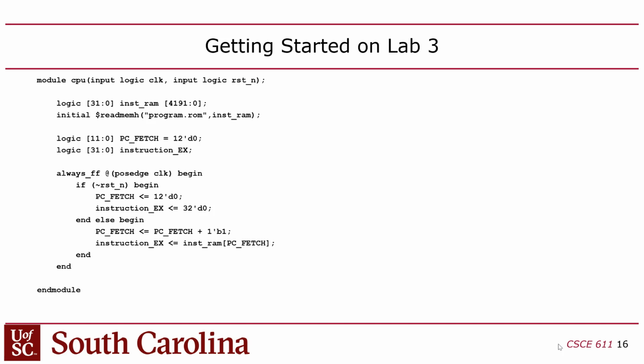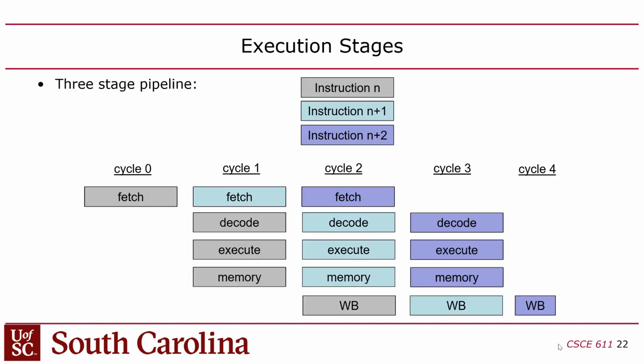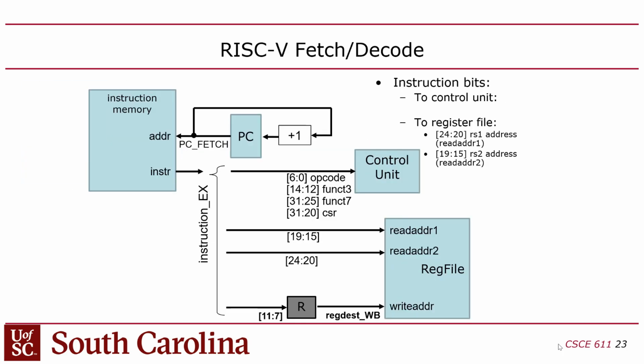We've got the program counter, incrementer, and the instruction RAM all inside this code, right? So you can see that the block diagram and the behavioral code are not the same. I mean, they do the same thing, but they're two different ways of showing what's going on in there. Structural versus the behavioral code. Okay, so basically you just have the program counter that mindlessly increments because we don't have branches and jumps yet, so it always marches forward by 1.